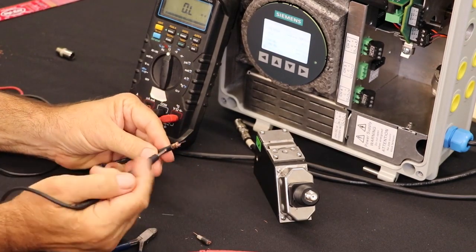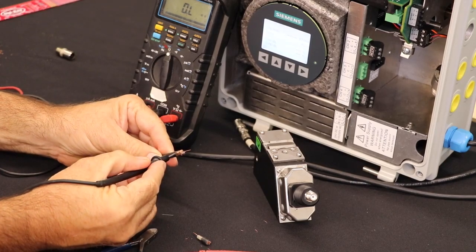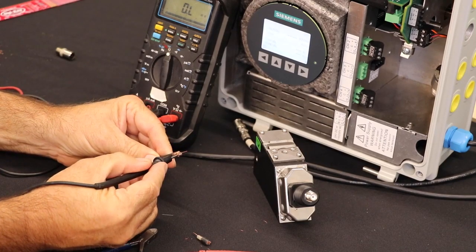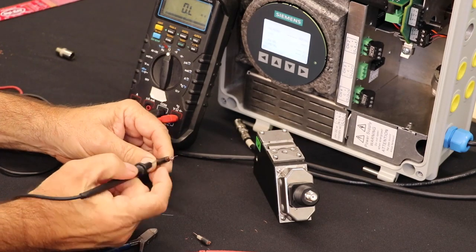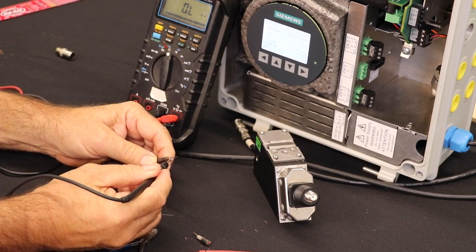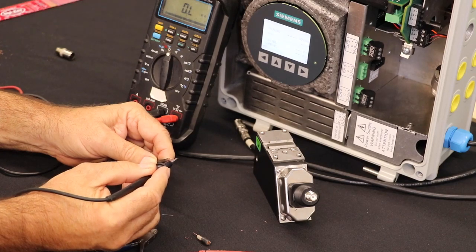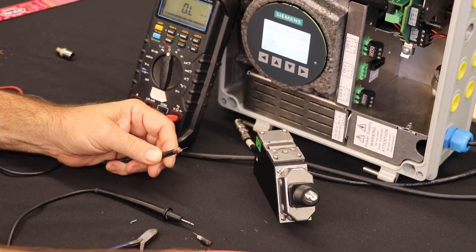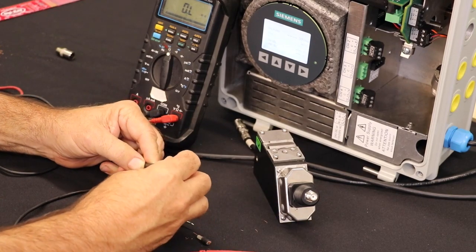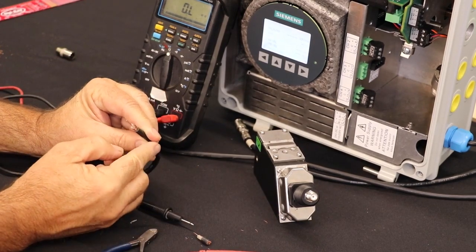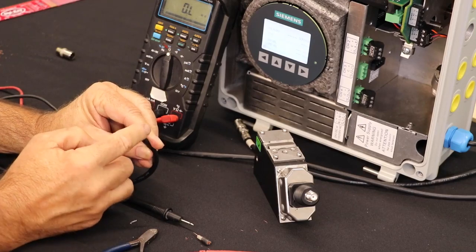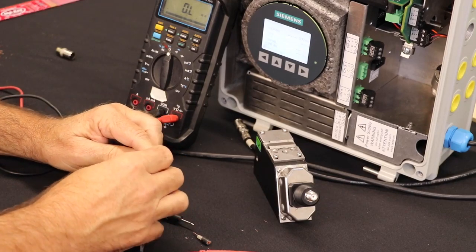The length from the outer insulation to the end of the inner insulation is 1/4 inch, and from the end of the inside insulation to the end of the center conductor is 3/8. And then you just want to, well, first make sure no whiskers are touching the center conductor, and then just tighten this back on.